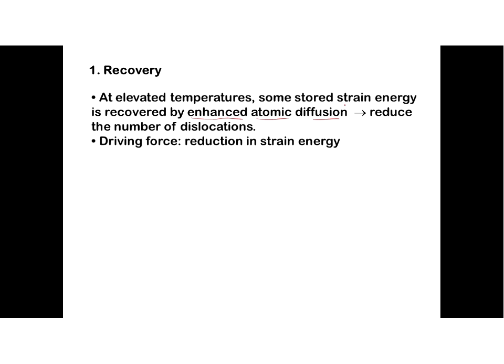Great. So at elevated temperatures, some of the stored strain energy is in fact recovered by enhanced atomic diffusion because it's warmer. This reduces the number of dislocations. All right? What's the driving force in that? It's the reduction in strain energy.